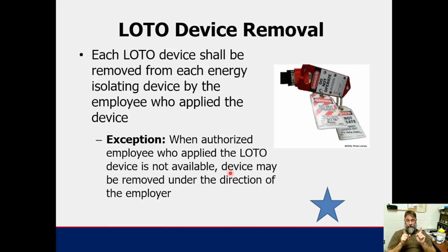And everywhere I've worked, and this may be across the board, I don't know, a lot of these places, if somebody other than the authorized employee removes that lockout tagout, it is an automatic fireable offense. So when in doubt, if you see a lockout tagout on a machine and that is your machine that you're supposed to be running, you need to contact your supervisor.